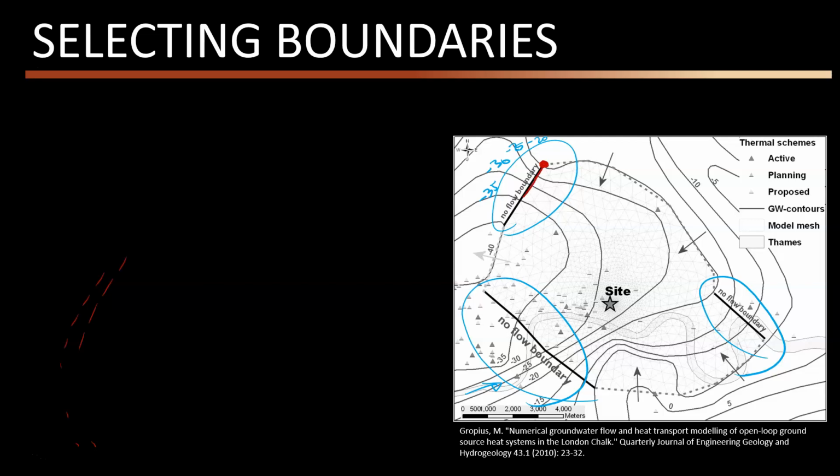if I want to look at how water moves, here I can draw a perpendicular line, and I can draw this line. So it means that the water moves like this. So I define a no flow boundary condition here because the water moves like this here. So there is no flow in this direction. The water moves parallel at this location like this. Okay, so that's why I define a no flow boundary condition here.